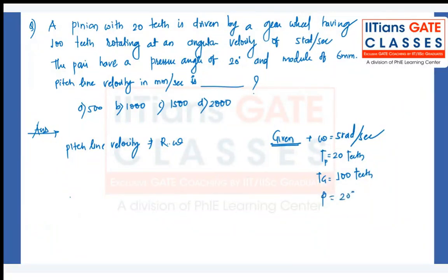Pressure angle is 20 degree. So you know how to calculate the R. R is equal to mt by 2. We are talking about the gear because the gear with 100 teeth is rotating at an angular velocity of 5 radian per second. So this is your omega of gear. So R of the gear is equal to module into number of teeth on the gear divided by 2.